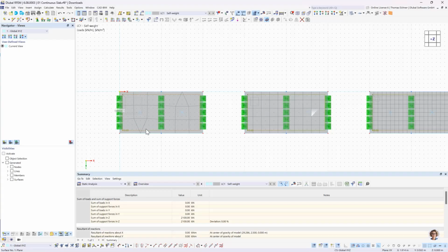And that's the point in the next figure. We can see 5 elements here. I learned some rules in my studies, and the rule was that 6 elements between supports for a single span beam should be good.